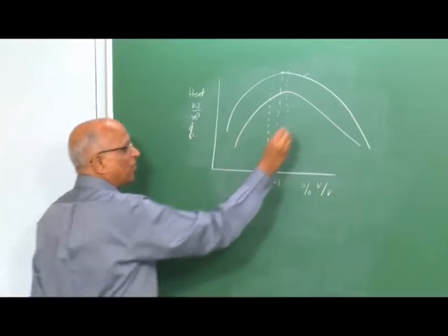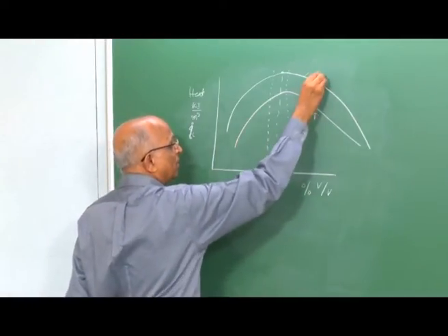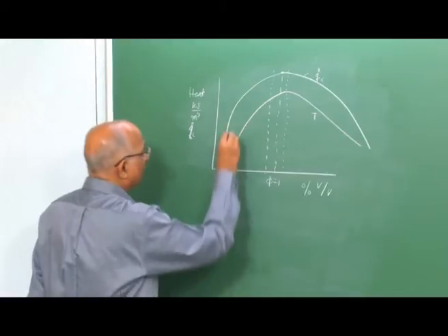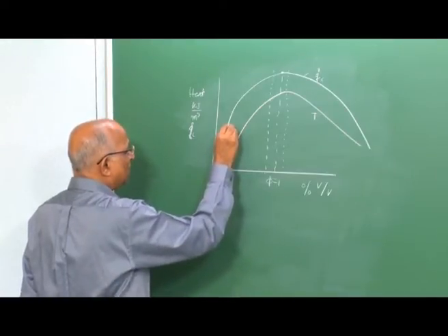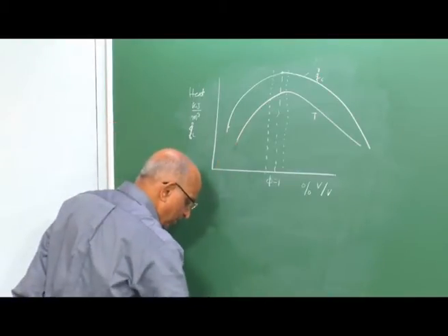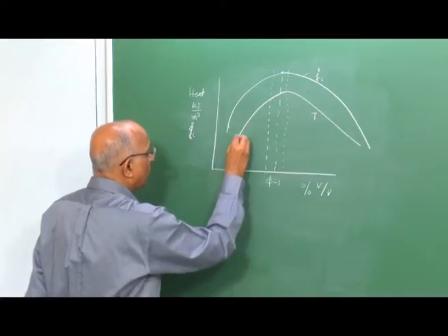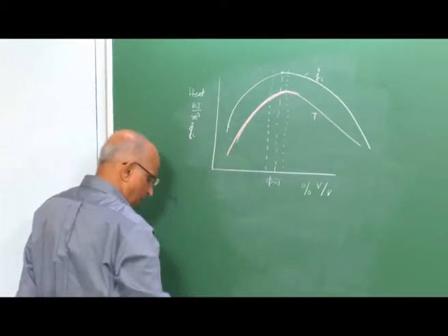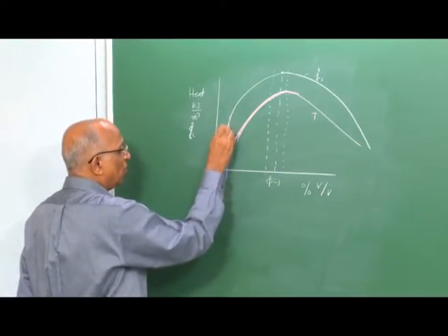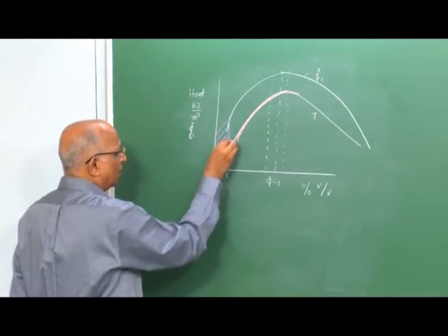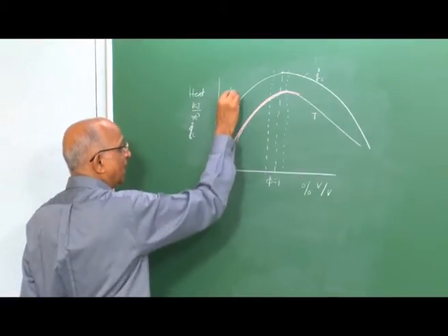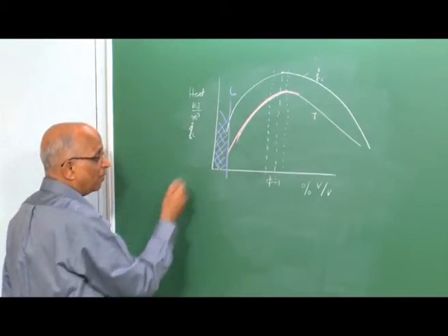Therefore, this is the type of temperature I get, and this is the type of heat release I get, Q dot C over here. If my temperature and heat release are less than some value, let us say at this condition of heat release, for which I extrapolate the temperature curve to something over here, this is the type of temperature curve I have. Maybe at this particular value the heat release is so small and the temperature is so small that below this the mixture cannot really propagate a steady flame. Well, I say L is over here; in this case I do not get a flammable mixture.